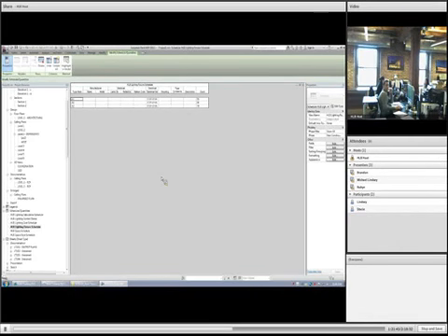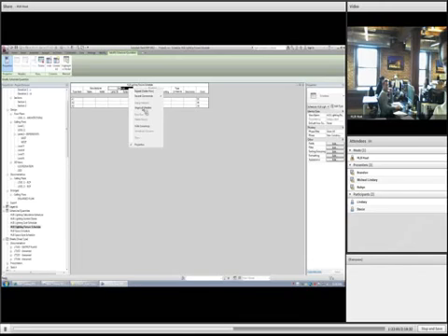Okay, so we had some headers that were grouped, right? We're going to ungroup those headers. You can't really click in there because you can start to change the text, but just left click and drag through the grouped header, right click, and you can hit ungroup headers.